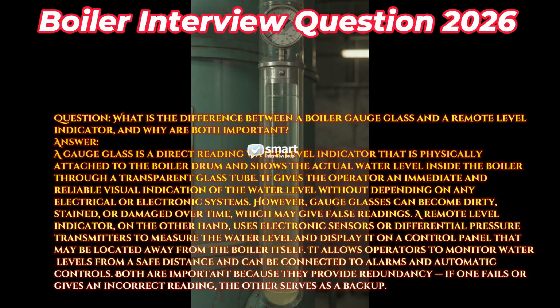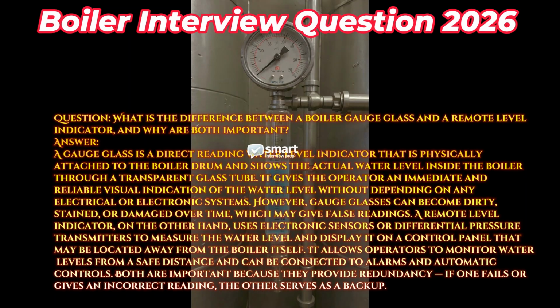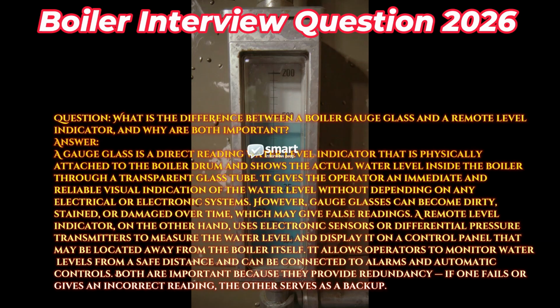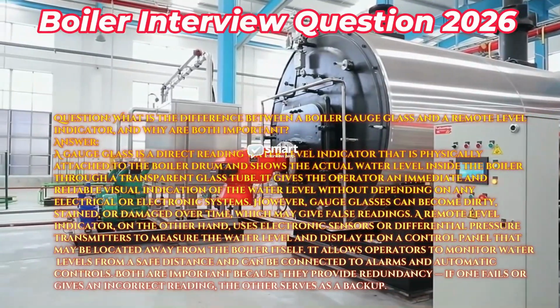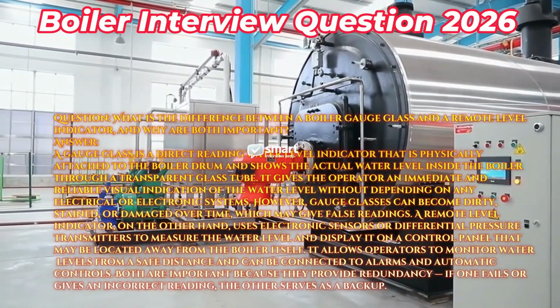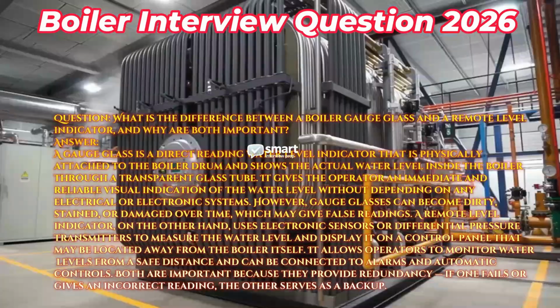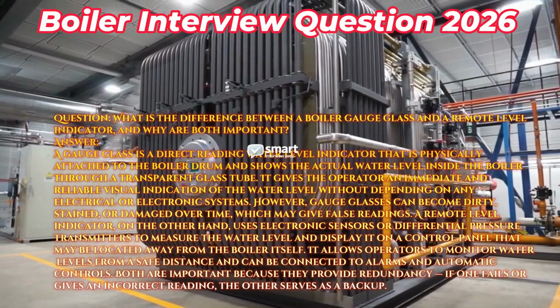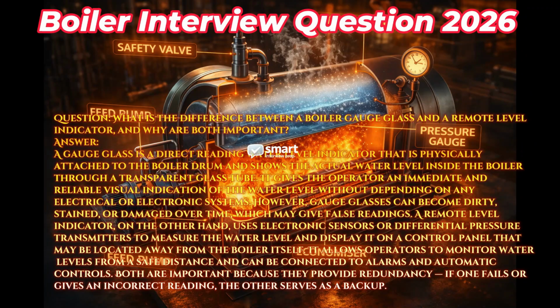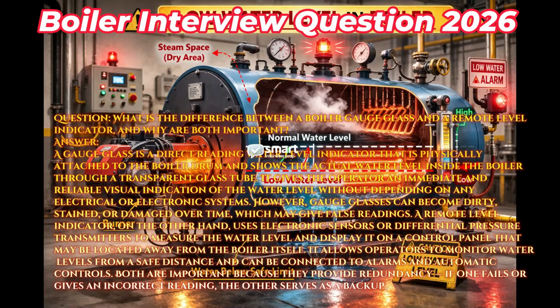Question: What is the difference between a boiler gauge glass and a remote level indicator, and why are both important? Answer: A gauge glass is a direct reading water level indicator that is physically attached to the boiler drum and shows the actual water level inside the boiler through a transparent glass tube. It gives the operator an immediate and reliable visual indication of the water level without depending on any electrical or electronic systems. However, gauge glasses can become dirty, stained, or damaged over time, which may give false readings.